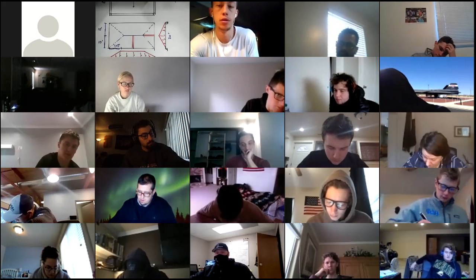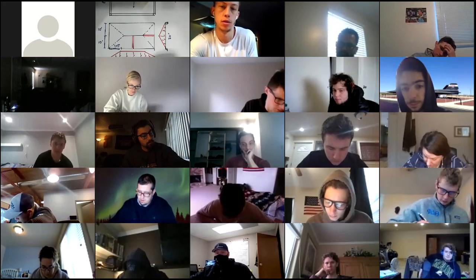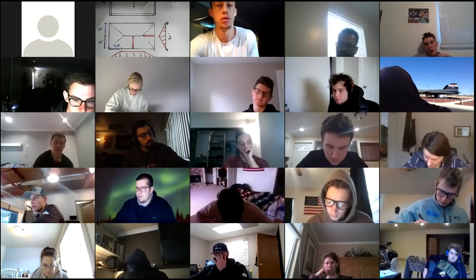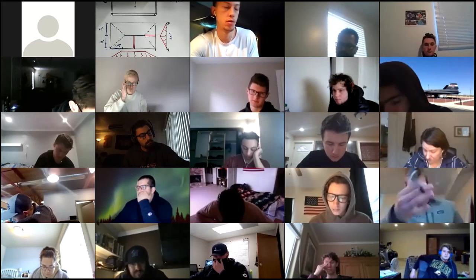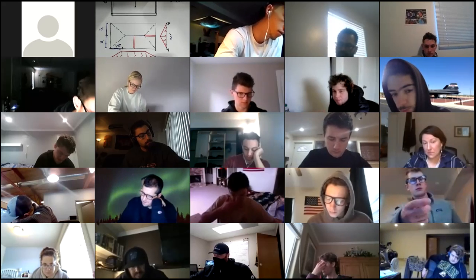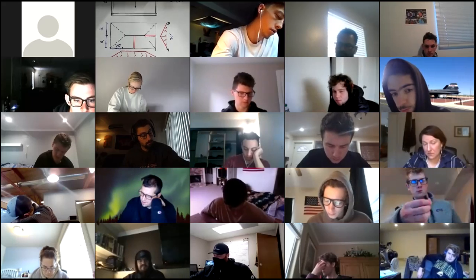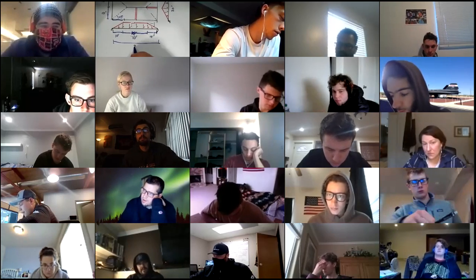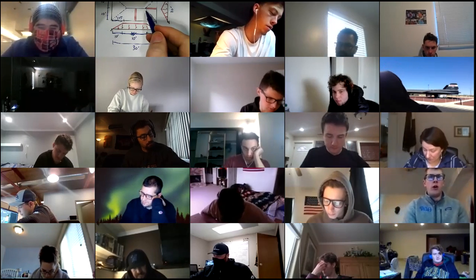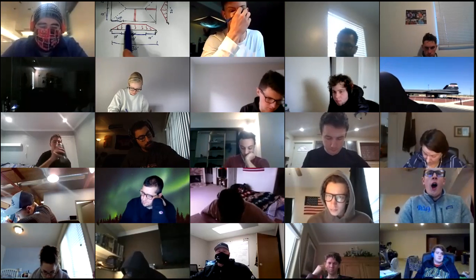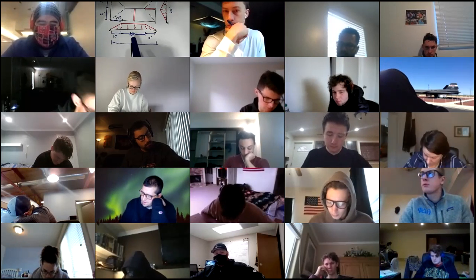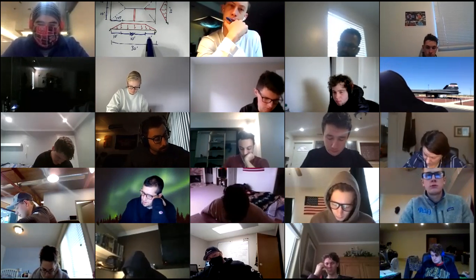Also 10 feet. Yep. Why? The easy answer is, it's a 45 degree triangle. 45 degrees means that the leftover space, now I put the 30 foot in a bad spot here, the leftover space then has to be 10 foot so that the overall is 30 foot, right? I didn't do a great job of getting this perfectly to scale, because each one of these should have equal widths of 10 feet. But this middle 10 feet is whatever is left over after you do the 45 degrees.